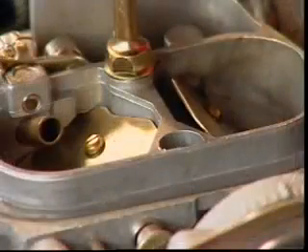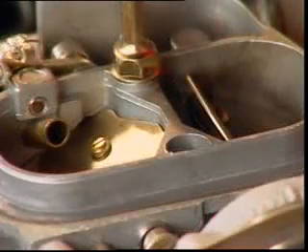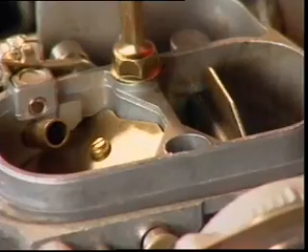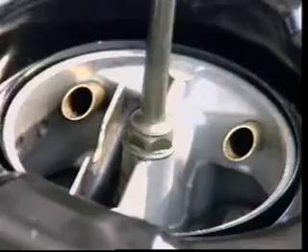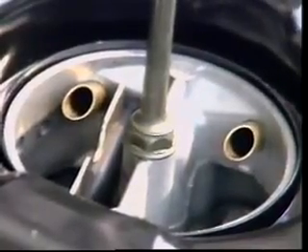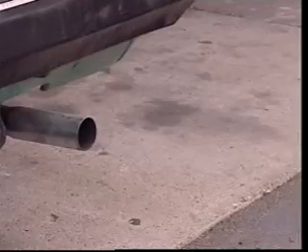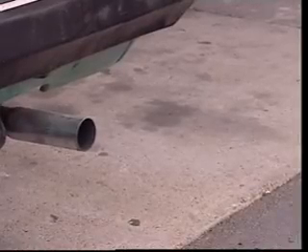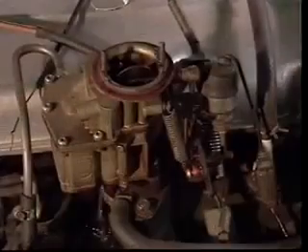Most are controlled automatically, so that the valve is closed when the engine is cold and opens progressively as the engine warms up. When the engine is warm, the fuel drawn into the manifold during starting vaporizes readily, and the engine can be started without the aid of a choke. The choke should operate as briefly as possible. Overusing it produces rich mixtures that cause exhaust pollution and increase fuel consumption.